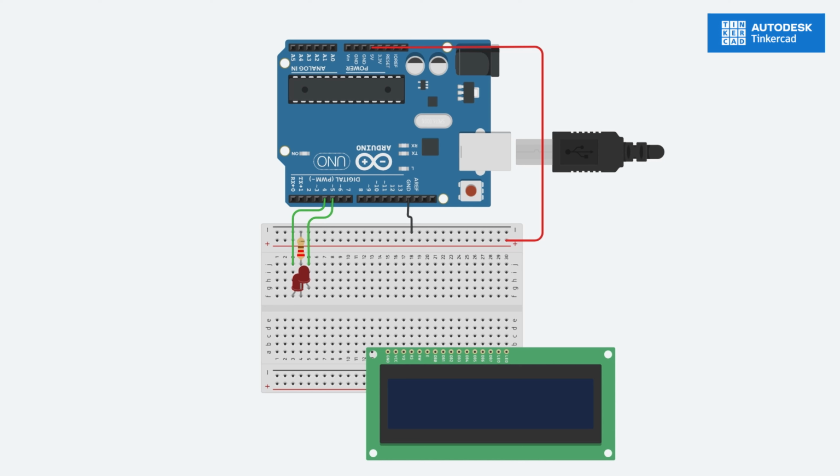After this, we'll connect the buttons. First, we can take the ground connection and pull it into the lower bracket as well. Then we can add both of the buttons. Then we can connect the first button to port 2 and the second button to port 3. We can then connect the first button to ground with a resistor as well as the second button, and now we can see if this layout works.